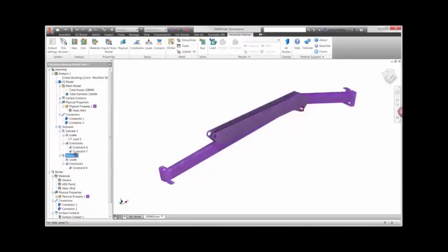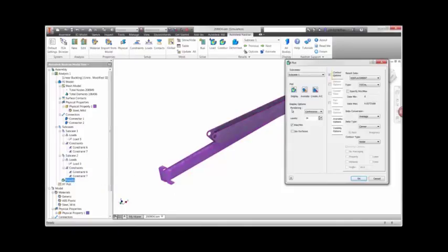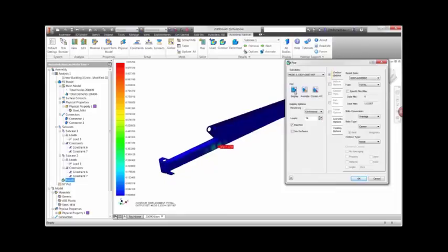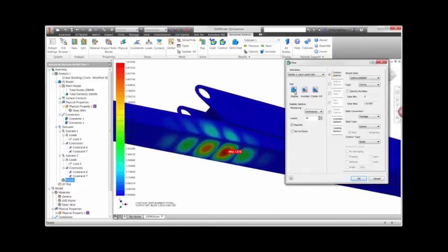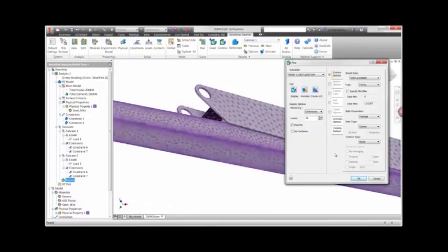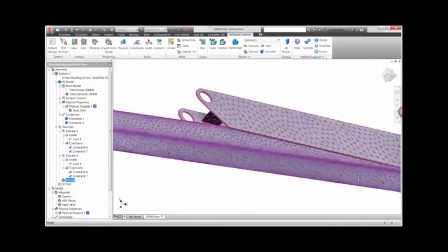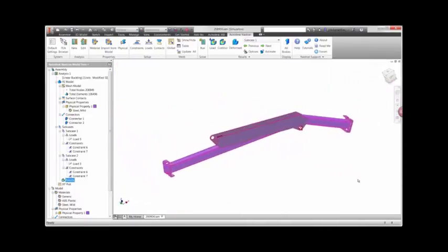The buckling analysis will result in a list of eigenvalues. These are scale factors on the applied load that indicate the actual buckling load. The first one for this model is just over 2,600 newtons. Since we wanted a minimum of 20,000 newtons, this is clearly a problem, and we may want to make modifications to the model dimensions to avoid catastrophic failure for larger loading conditions.